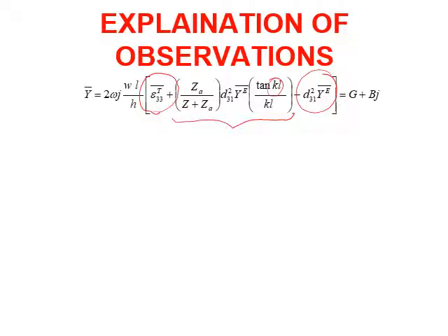So we can do one substitution here. Let's say we write this as epsilon 33 (1 minus delta j). We have defined earlier what delta is. Delta is the electrical loss tangent, very similar to mechanical damping, so it is the electrical equivalent of the mechanical damping. And then we have this part.